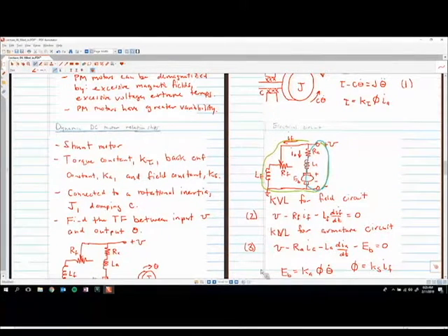Okay. So revisiting our discussions on the moving coil transducers that we talked about, probably Monday last week, we talked about how these are combined electromechanical systems, right? So the equations of motion interact. You can see this again in that we have our equation that mostly describes our mechanical system, but the torque on this mechanical system is a function of both the flux, which is related to the current running through the field circuit, and also the current running through the armature circuit, right? So it's linked in that fashion.